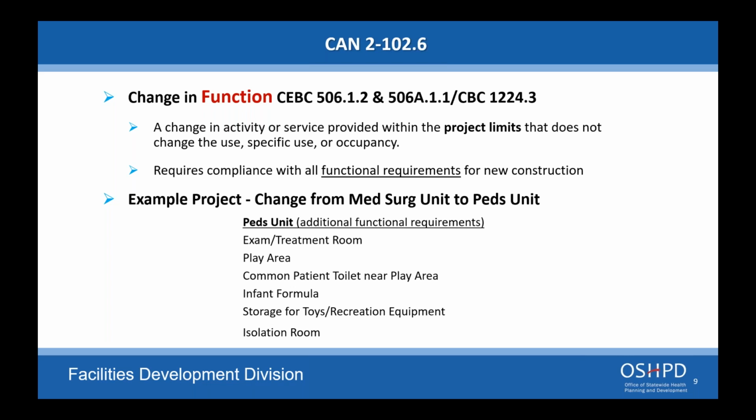The other thing, if you do not have those, you do have to present to the OSHPD team basically a proposal based on current code. This is what's required in these rooms, and we're going to balance it to that. So there is a level of rebalance that would be required.